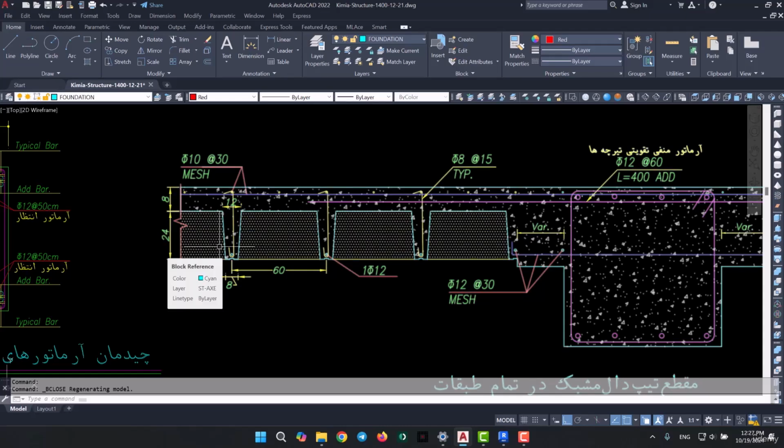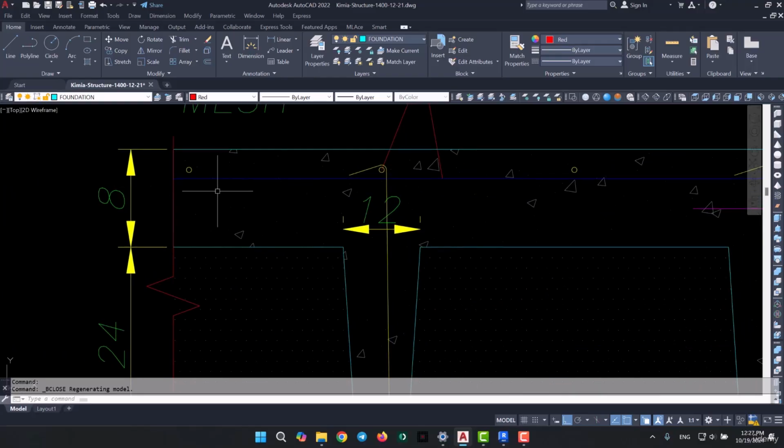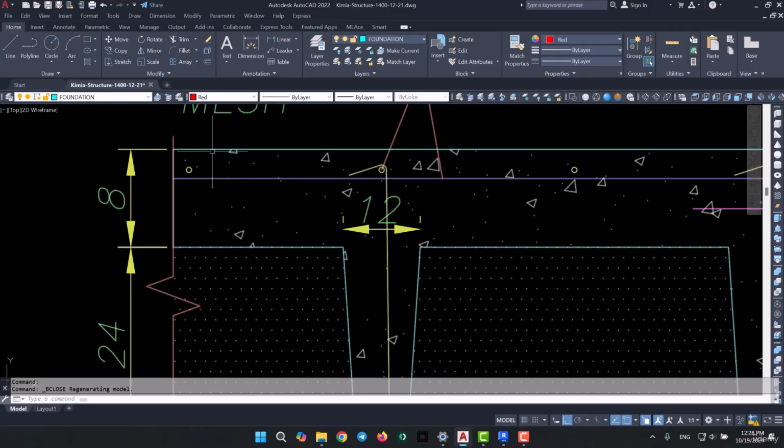There's also another thing. You've probably seen the waffle families in Revit, and I'm going to show you 3 of them. You probably also know that there will be concrete going over the waffles. For example, do you see this line? This is in fact the end point of the waffle, and then we've got more concrete going over it.